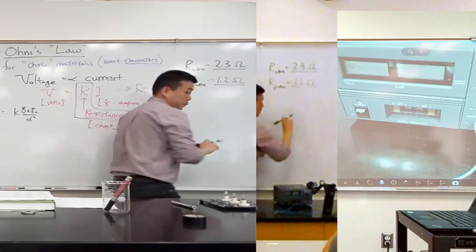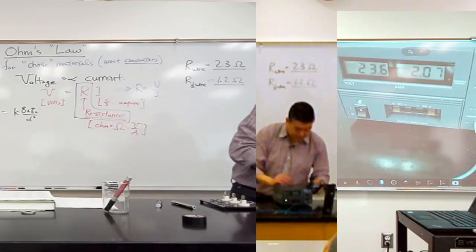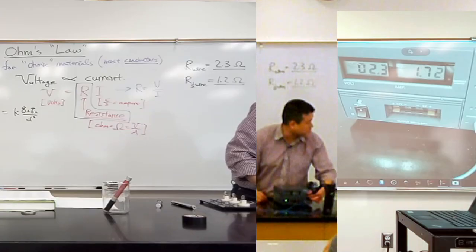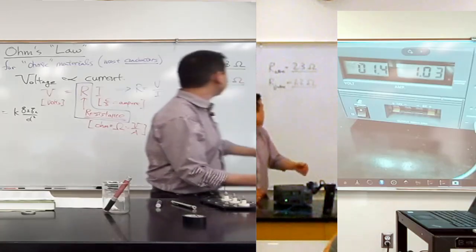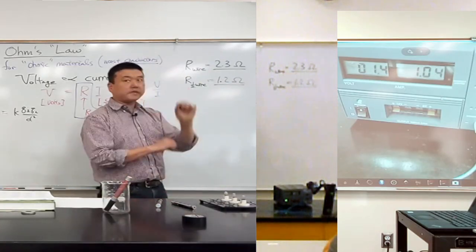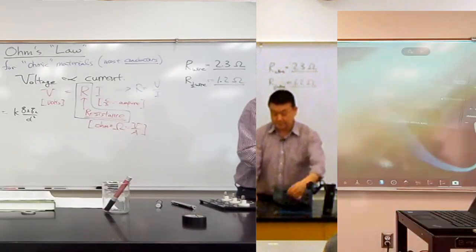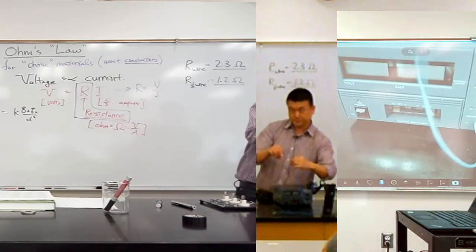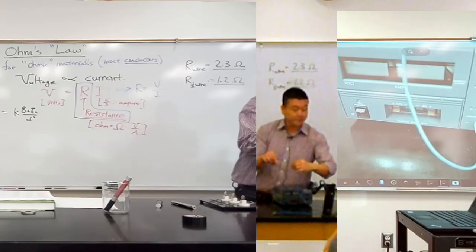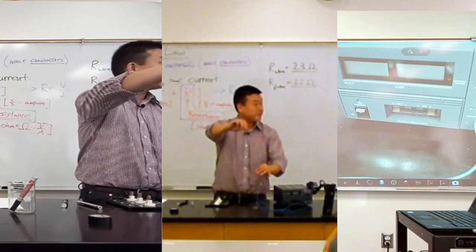1.2 ohm, which means, let me actually do it this way. So having turned it on, let me reduce the voltage until the current goes down to 1. So right now I see 1.4 instead of 1.2. And that small difference is actually the amount of resistance in this wire. Because, as I keep saying, this is only a piece of wire. It's not some specially made resistor.